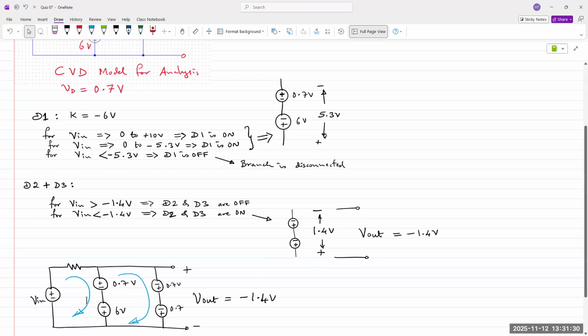The one thing that I'm going to try with the simulation is, instead of having series resistance in the diode model in LTSpice, I'm going to run with 0 or 1 milliohm resistance and simulate it and see if it matches with this assumption. See if we can figure out if there's any extra voltage drop across the resistor. And if it doesn't, then we'll discuss it on Friday.